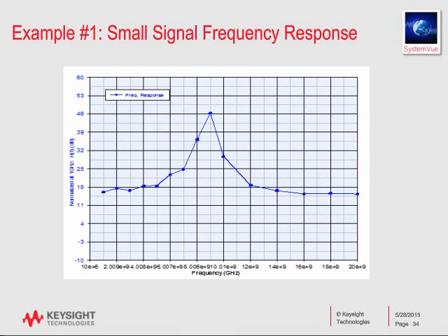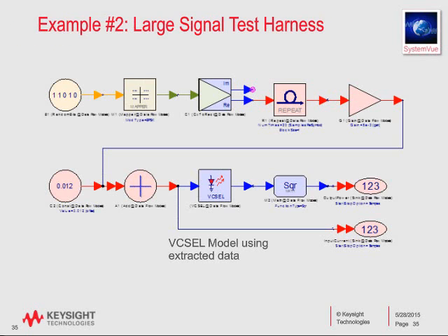And here is a swept frequency model. Here we're looking at the frequency response on the lower axis versus, we'll call it, an S21, but it's for optical power. So in other words, we're looking here at electrical energy into optical power. And you can see here that there's a definite peak, but that the response is actually good to probably in the region of 10 to 12 gigahertz. That's for small signals. So can we do large signal testing?